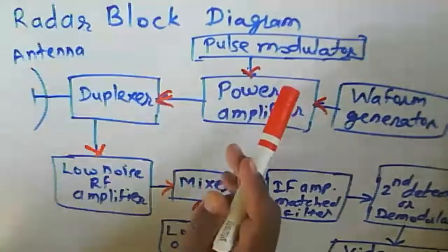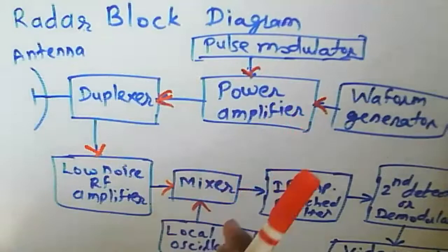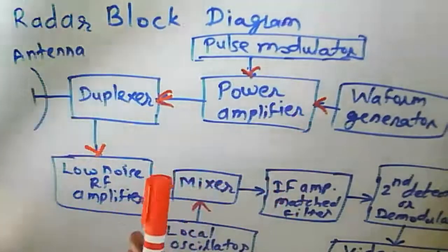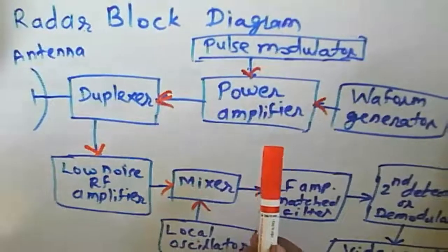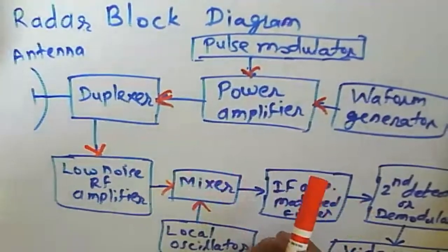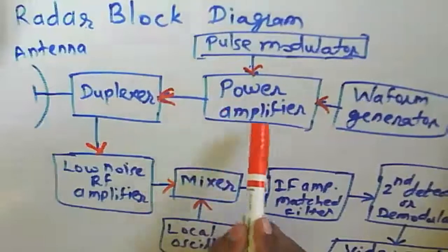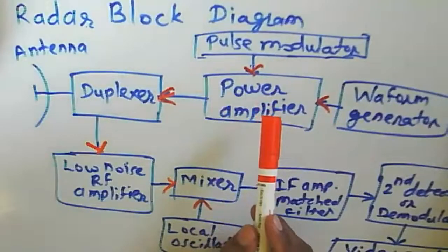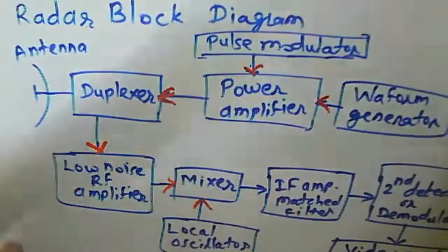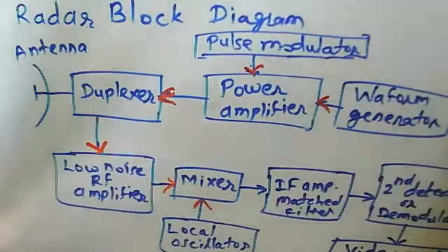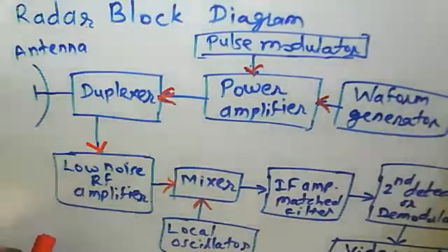So what will be the device that is useful for the transmitter? Generally we require a large power to be transmitted there. So that's why we are supposed to use a power amplifier. If we are using an X band, for example the microwave frequency range present in our department, X band components, in that case we consider a klystron or a Gunn, because it generates 8 gigahertz signal frequency there.